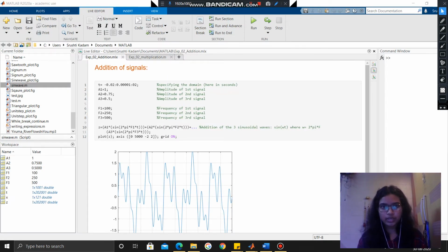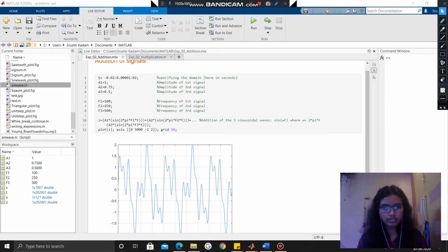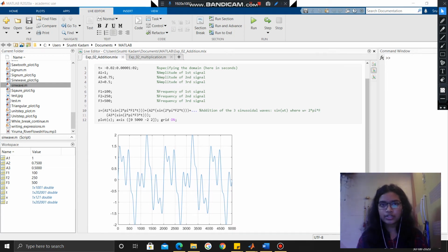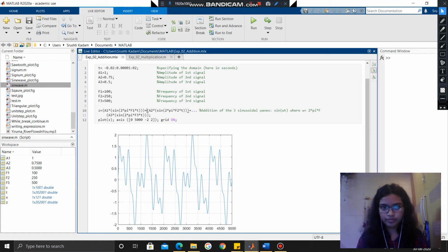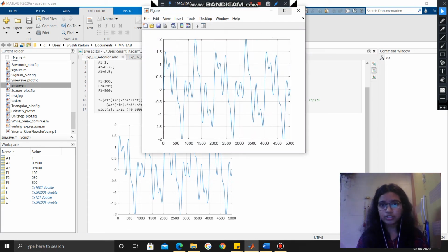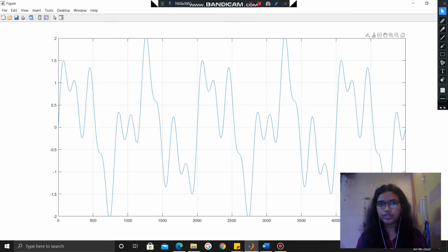Next, we go to the C part of part 1, that is addition of signals. I have created three sine waves, and the amplitudes were given as 1, 0.75 and 0.5 respectively, and the frequencies were given as 100 Hz, 250 Hz and 500 Hz. You know that sine of omega t, where omega is equal to 2 pi f. That is what I've written, and I directly added them with a plus sign in between. After plotting them, this is the curve that we get by addition of 3 sinusoidal waveforms of different frequencies.